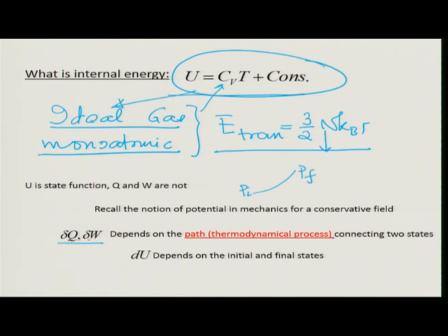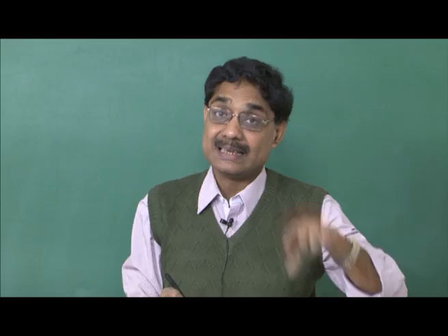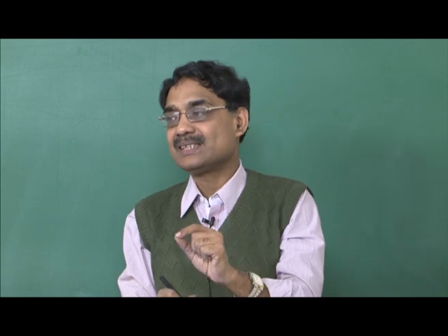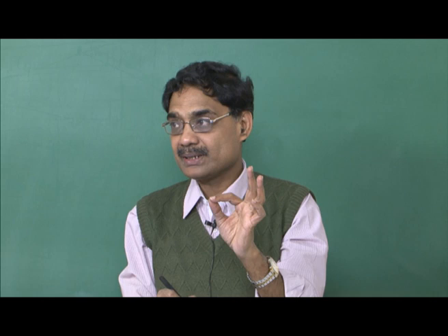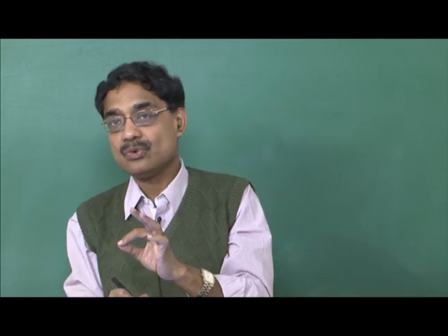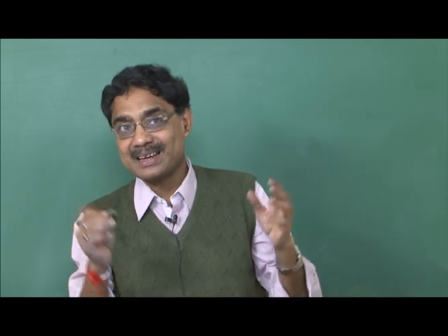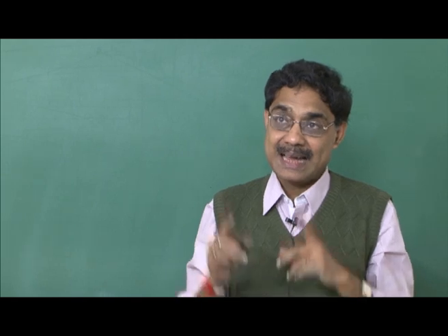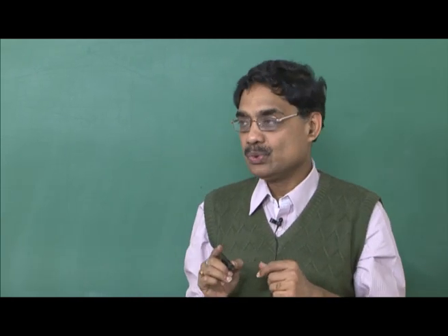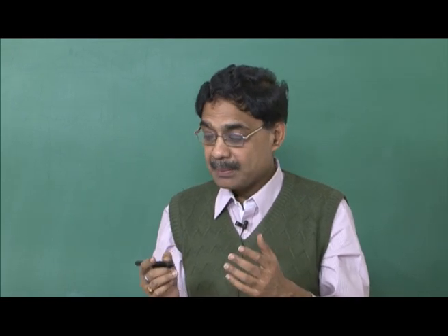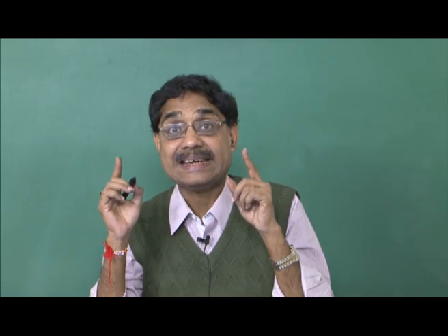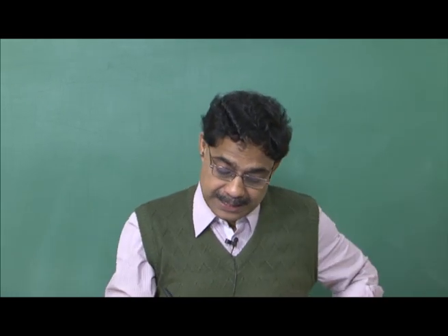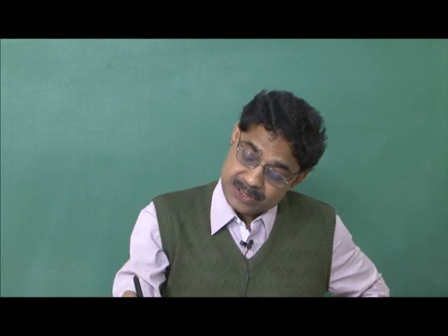This delta Q and delta W depend on how I have reached from the initial to the final state, but dU does not depend on how I went from the initial to the final state. Rather, it depends only on the initial state and the final state. That is a very important concept which I will explain from the point of view of mechanics, where you already know there is a concept of potential for a conservative force field. That I will generalize here to explain what this internal energy is and what I mean by the terminology that it is a state function. So, I end this by saying that this quantity actually is a state function.